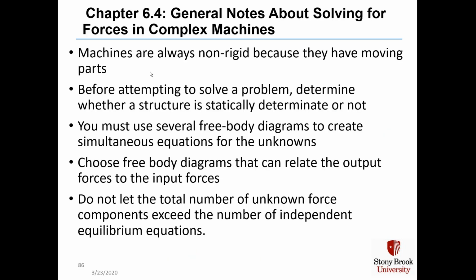Here are some general notes about solving for forces in complex machines. First off, machines are always non-rigid because by definition they have moving parts. Before attempting to solve a problem, you must determine whether a structure is statically determinate or not. You usually have to use several free body diagrams to create simultaneous equations for the unknowns, and you should choose free body diagrams that can relate the output forces to the input forces. And make sure not to let the total number of unknown force components exceed your available number of independent equilibrium conditions.